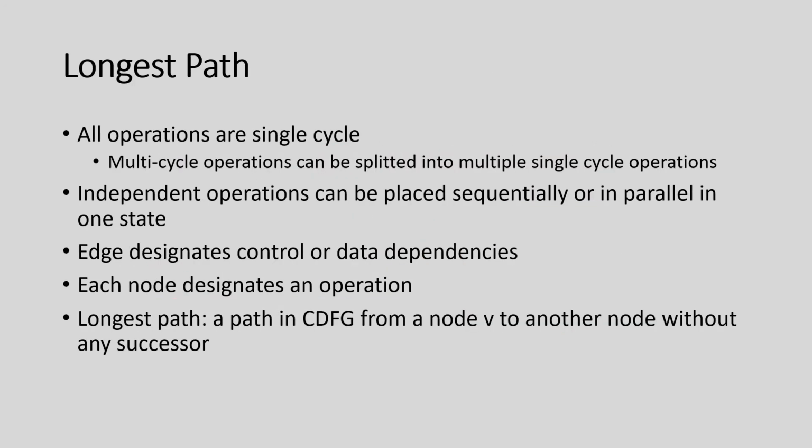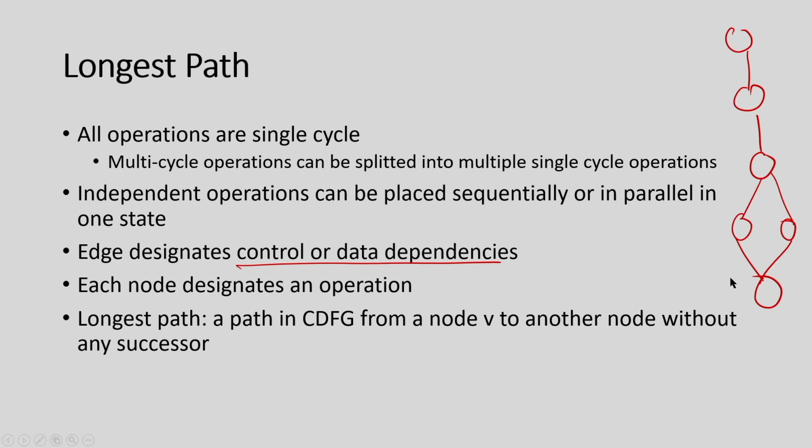So, the first problem is that you have the program, and you represent it using paths. How to do that? We construct a special kind of CDFG here. You have the program, and every operation you are going to represent by a state now. Every operation is a state, and whenever there is a control flow or data flow, you are going to add an edge. So, if there is an if else, it is going to be an edge like this.